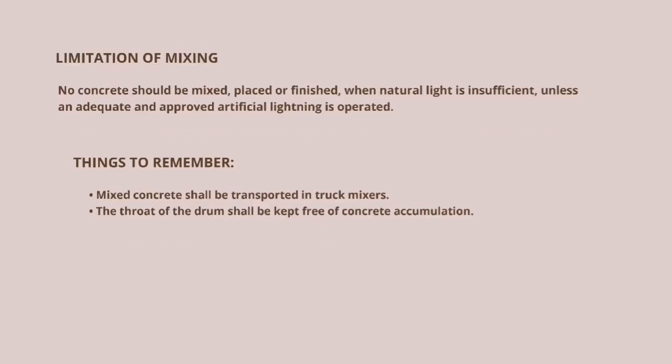Limitation of mixing. No concrete should be mixed, placed, or finished when natural light is insufficient, unless an adequate and approved artificial lighting is operated. Things to remember in limitation of mixing. First, mixed concrete shall be transported in truck mixers. Second, the throat of the drum shall be kept free of concrete accumulation.